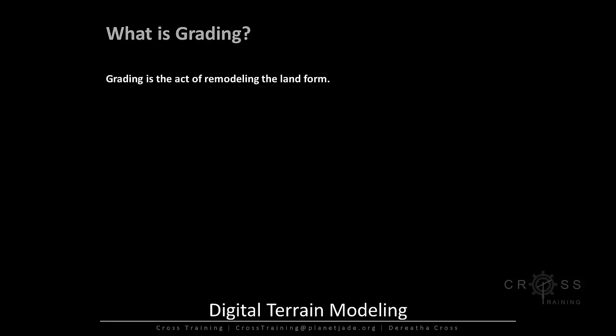Grading is the act of remodeling the landform. So your design will sit on a terrain base, and you will have to sculpt this terrain base so that your design is somewhat feasible. Of course, you want people that come in from the parking lot to be able to get to your building and not have to cross a ravine or something.